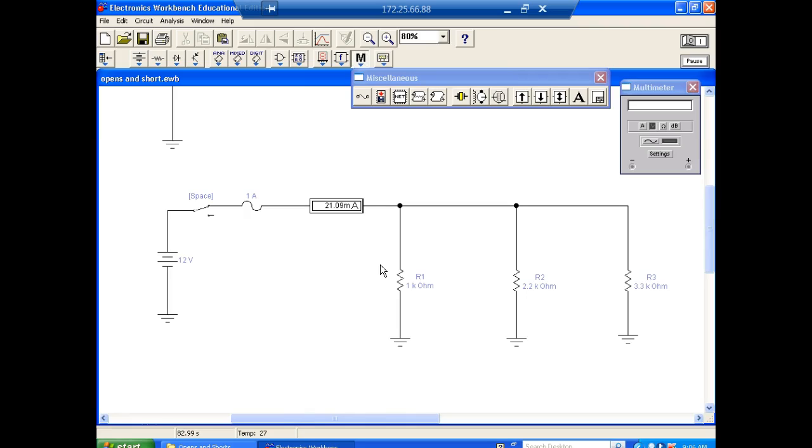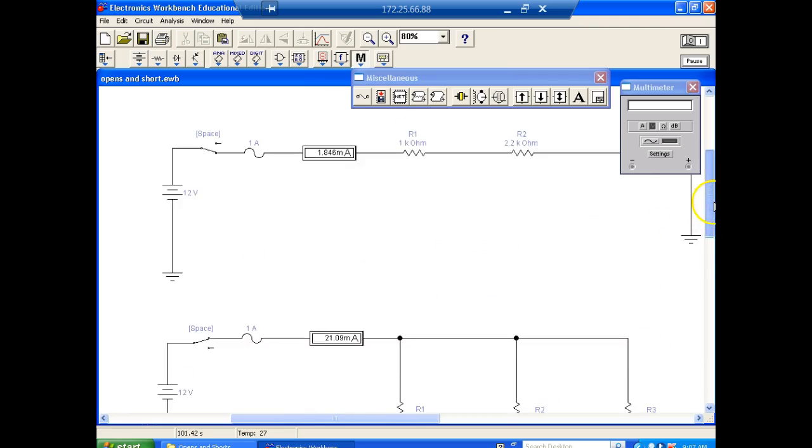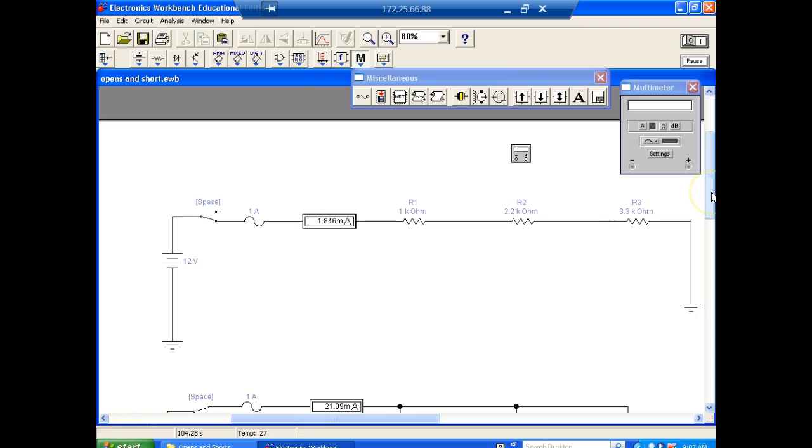So what happens is this is my return conductor. This is my source conductor. If this shorts right here, then that's going to do what? Short circuit. So parallel circuits, every short is a short circuit. Series circuits, every short is not a short circuit, but every open is an open circuit, right? You understand? And what you'll learn while you're in, you'll learn that parallel circuits and series circuits are just opposite of each other.